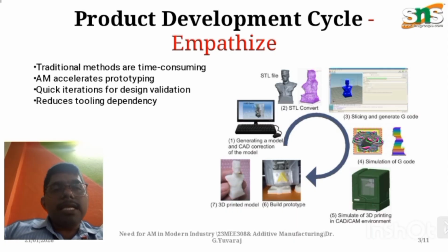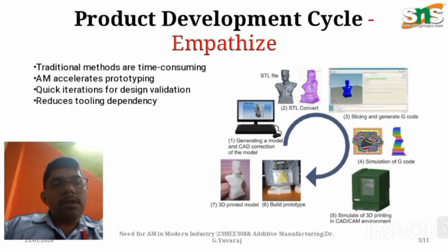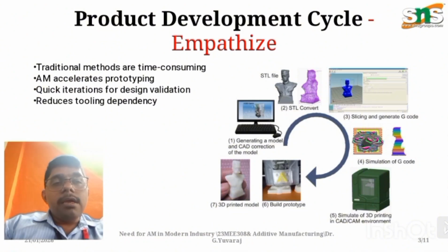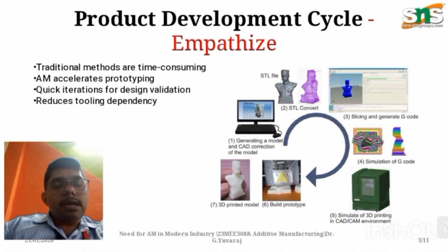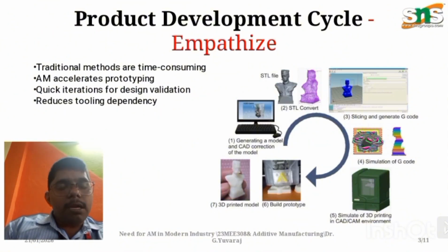Once the design has been done using software like Solid Edge, SolidWorks, or Creo, or any available modeling software, the CAD is converted into STL format, a standard readable format. The STL reads the shape and recognizes its points, so that it can be executed in production.